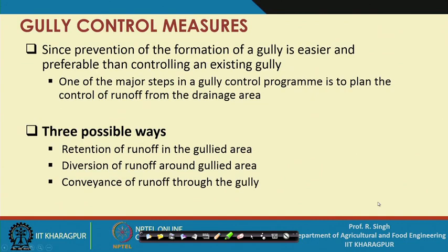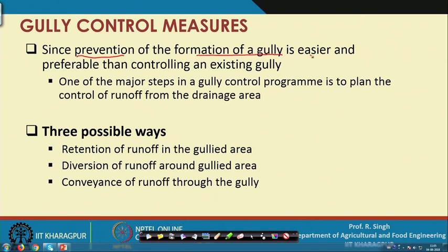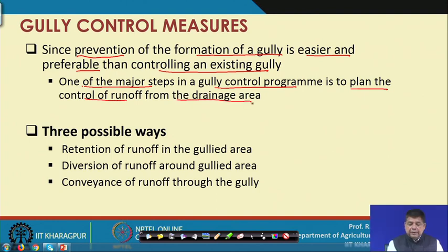So, let us start with the gully control measures. Since prevention of the formation of a gully is easier and preferable than controlling an existing gully, one of the major steps in the gully control program is to plan the control of runoff from the drainage area.